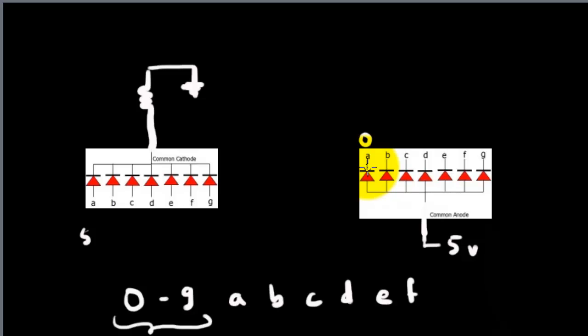So we'll go ahead and look at how we could use the 7 segment to display digits from 0 to 9. Now this is the arrangement of the 7 segments. Now what we have is the segments A, B, C, D, E, F and G, and then the decimal point. And we'll also write the hexadecimal code of the binary pattern that will generate here, because this is helpful when interfacing it with any of the controllers.